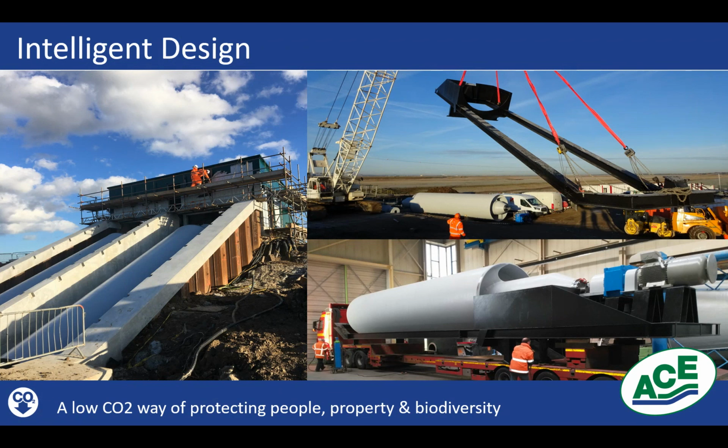On the left-hand side is the Archimedean screw, the kiosk being erected. ACE supplied not only the screw, but also the kiosk, the control panel, the non-return valves, and the stop logs. So we really did a nice turnkey project here. You can also see how it's lifted in, which once again helps because everything is modular. It's been made in the factory. It can be picked straight off the lorry, dropped straight into the civil structure.